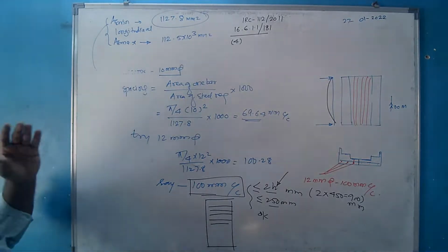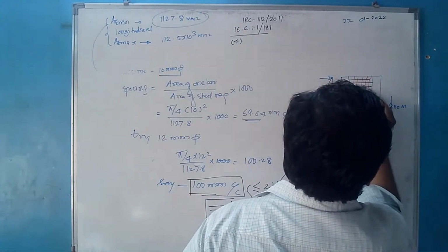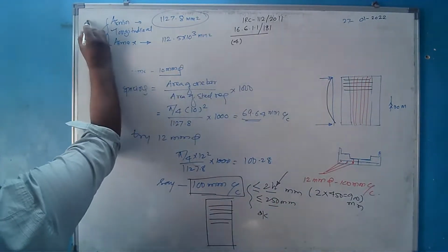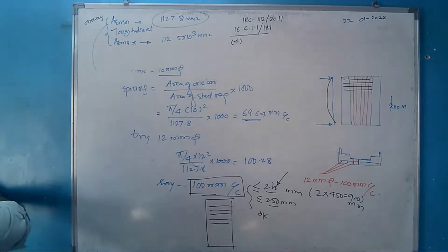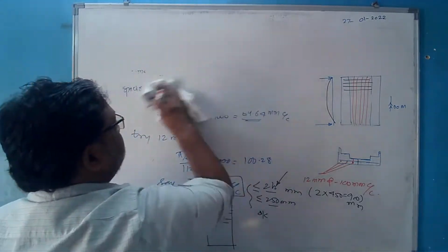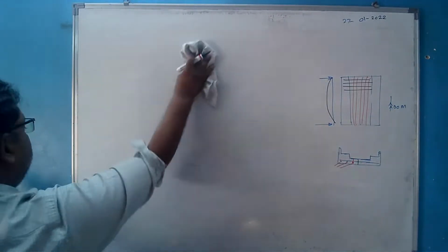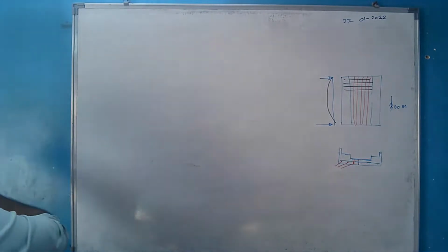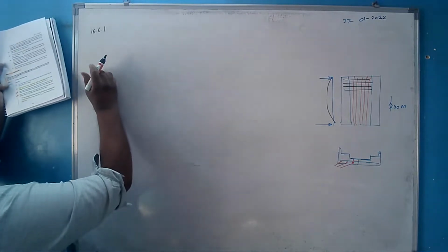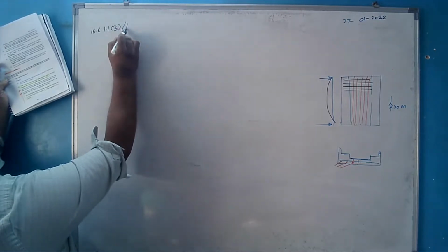Now, what about the reinforcement to be provided in the other direction? This is one-way slab. Now, what are the guidelines for the reinforcement? This is longitudinal. This is for one-way slab we have done. Now, the steel to be provided perpendicular to this. What are the guidelines for that? Please refer 16.6.1.1. It is part 3 of that clause on page number 181.